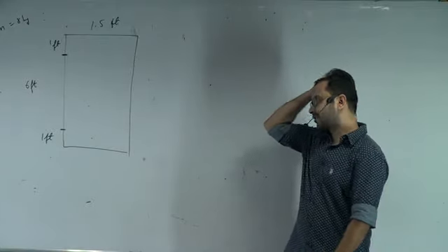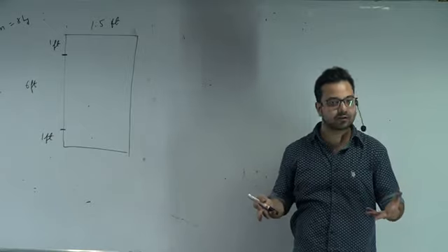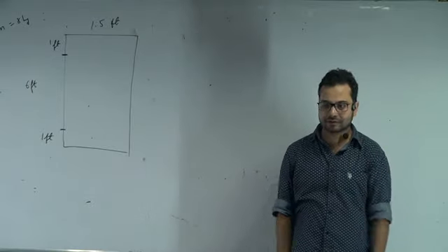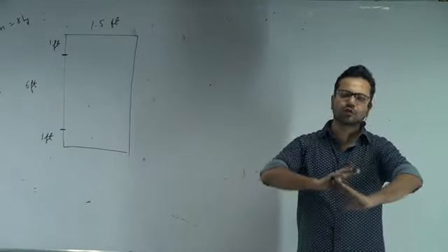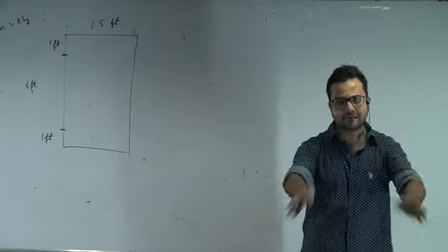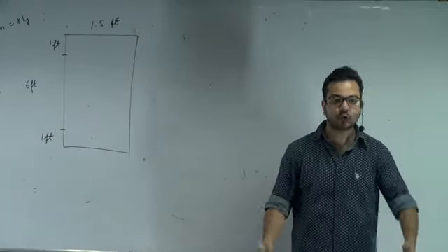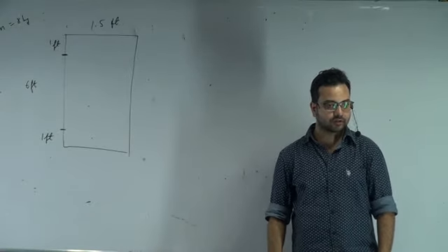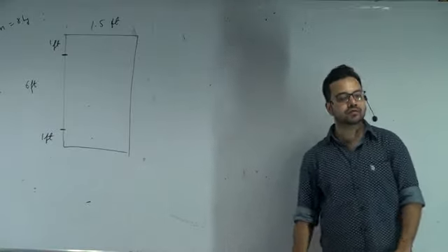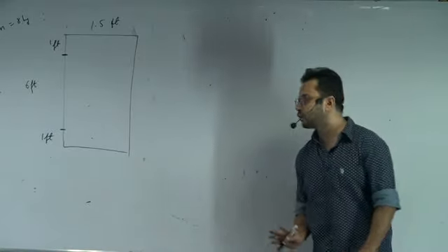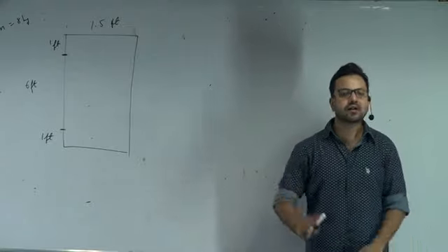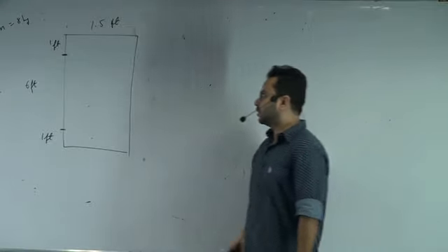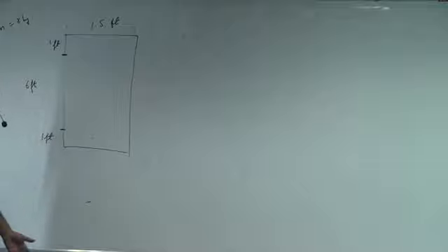Okay, but there is a way to find out, and the way to find out is your force equations and torque equations. Everything will depend on that. Hinge force could be in any direction. It could have any magnitude, it could have any direction. We'll deal with hinge forces in detail later on, but I want to introduce hinge forces. Hinge forces are a bit tricky to solve. So even when I'm drawing the free body diagram, I don't know in which direction the hinge force is going to act.